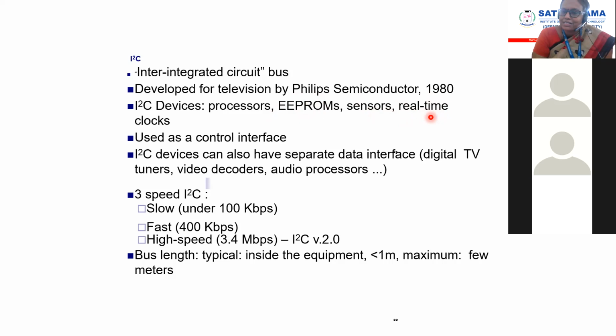I2C bus is mainly used in portable instruments, where devices like sensors, real-time clocks, analog to digital converters, digital to analog converters, and memory cards use I2C. Wherever I am connecting I2C devices, all the devices are slave devices. There is only one control, that is my master control.